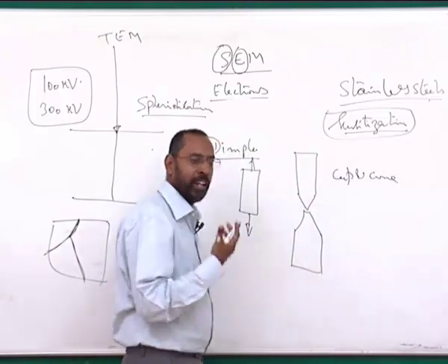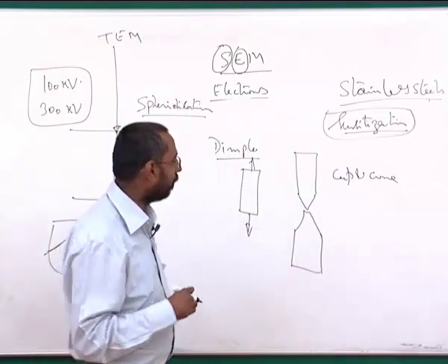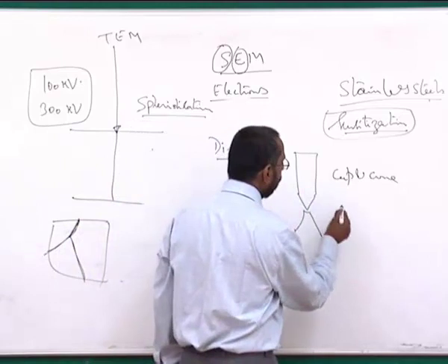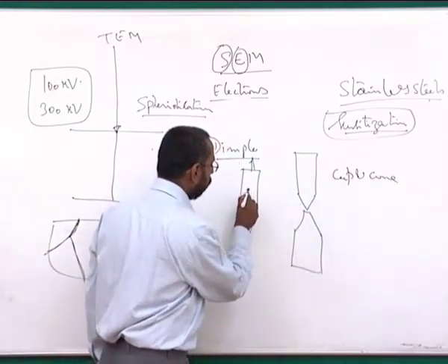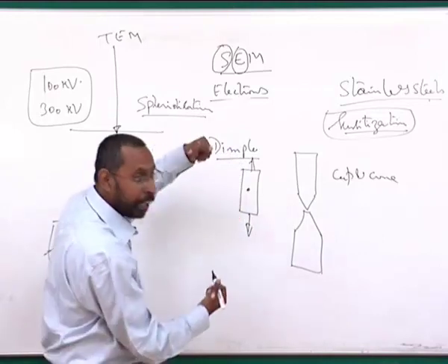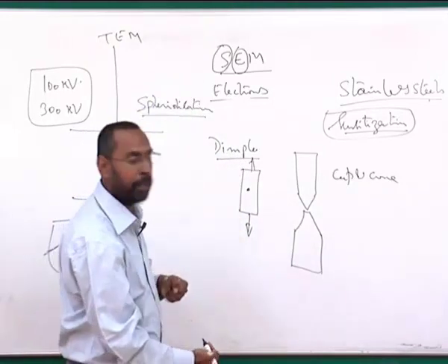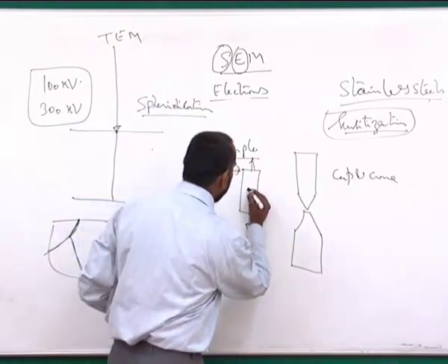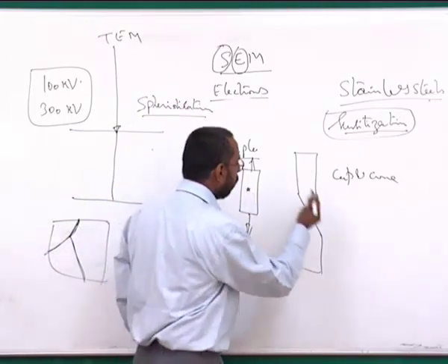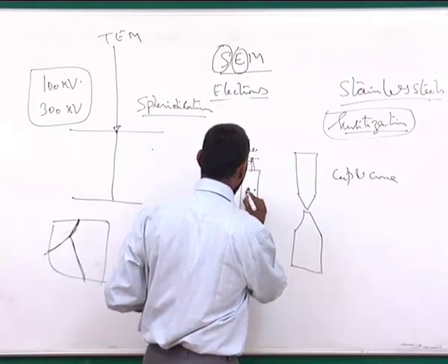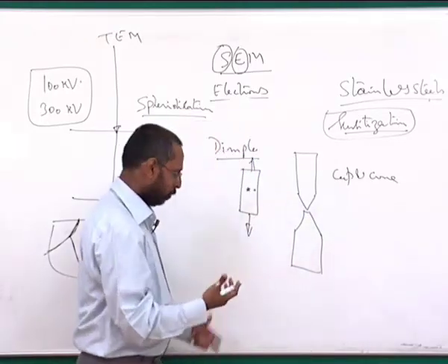Generally most materials have some inclusions, and the interface between the inclusion and the material gets separated because of the forces that we are pulling, and that separation can cause certain voids around that, and these voids get created at a number of places, and all of them join together.